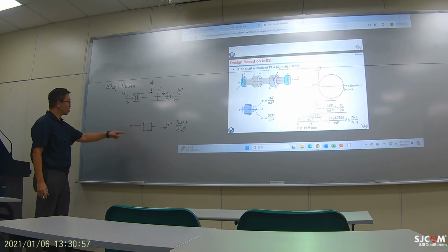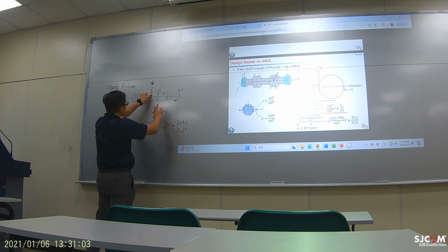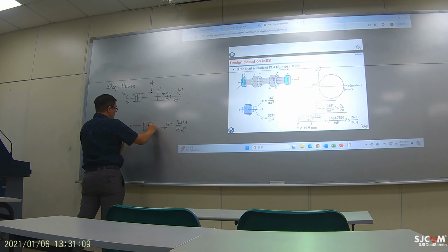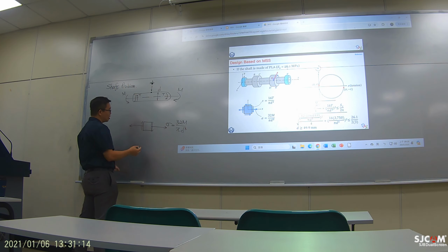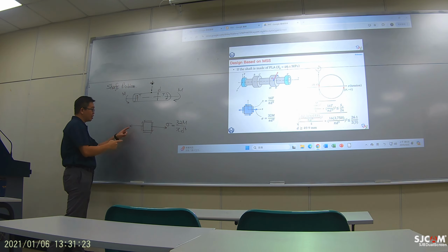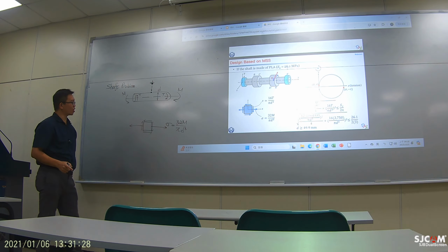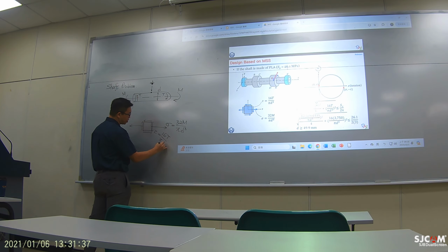Due to the twisting, you will have shear stress. If you view from the top, this particular position is being twisted like this. So the shearing force goes down on the right and goes up from the left. And usually it's coupled shearing forces, so over here you will have the opposite twisting shearing stresses in the other direction, so they balance out. So all these equal tau, and it equals 16T over pi d cubed.